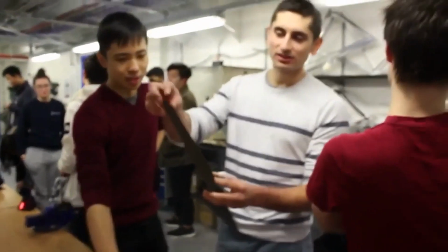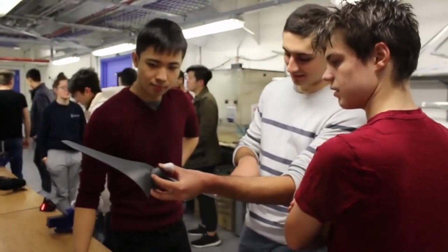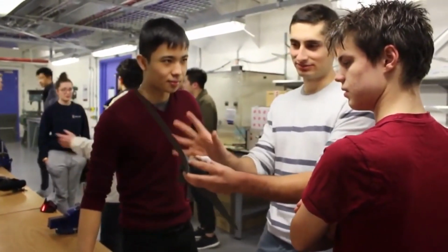Our swept wingtips were very thin and therefore fragile. This made sanding them to a smooth finish difficult. Surface roughness could have nullified any advantage contributed by the wingtip shape. Additionally, a pause during the manufacturing process led to lines printed along the length of both blades on the upper and lower surface of the blade, near its leading edge. This could have caused the boundary layer of the suction surface to trip, significantly lowering the performance of the blade.